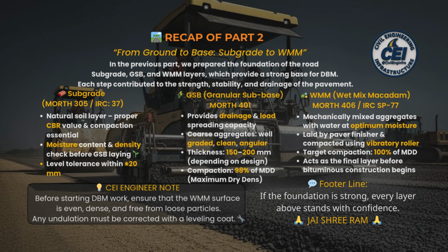CEI Engineer Note: before starting DBM work, ensure that the WMM surface is even, dense, and free from loose particles. Any undulation must be corrected with a leveling coat. Footer line: if the foundation is strong, every layer above stands with confidence.